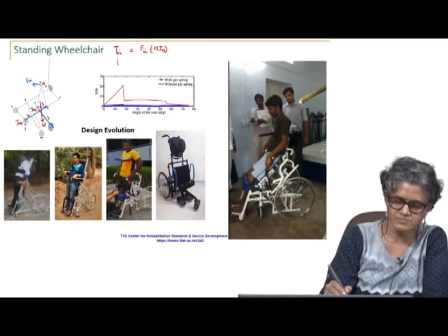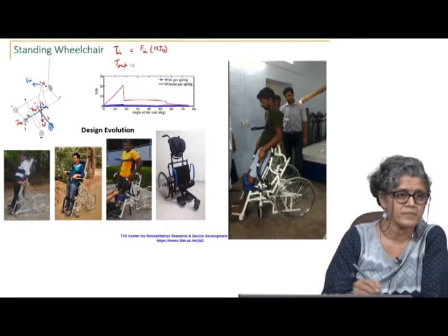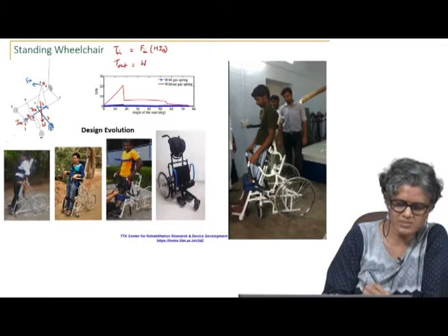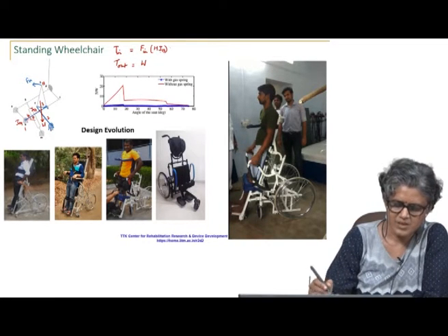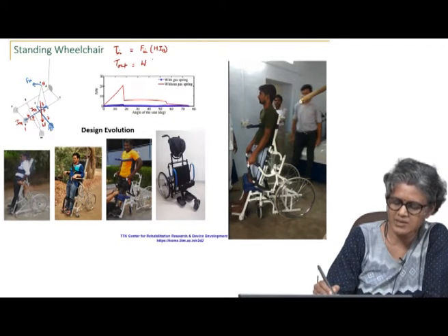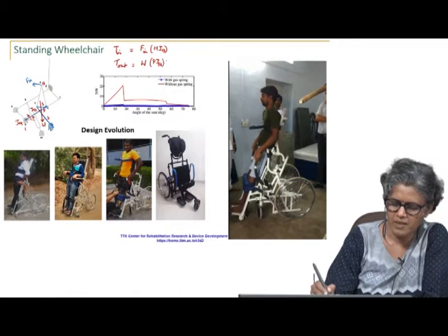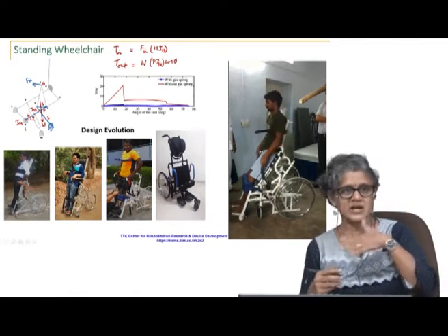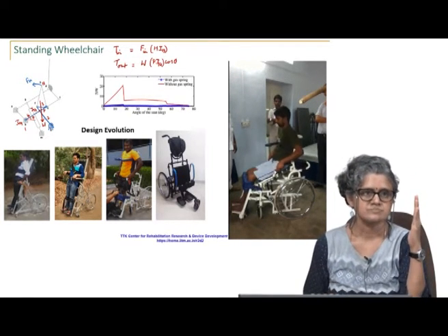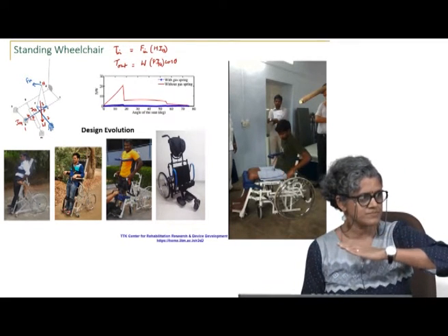The output torque that has to be overcome is W times cos theta, and let us say this is acting at a point P on that link, so P I14 cos theta. It is going to vary, but imagine at theta equal to 0 to start lifting, that is a pretty huge task to lift this weight.